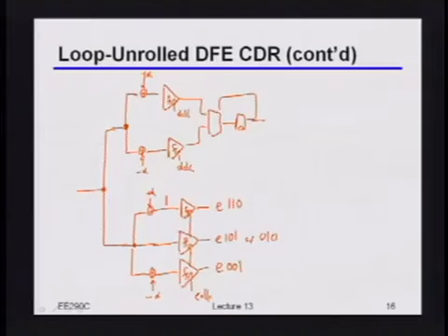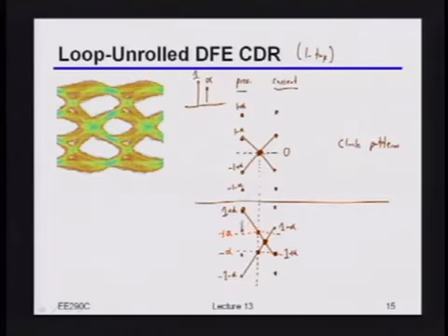But to do it live, I think has similar problems as what the normal loop unrolled DFE has, in the sense that there's really no analog level that you're looking for that gives you exactly that information. I guess actually, to be fair, the only saving grace here is that you really could look for this point in time here, but that would assume that you locked in the right place in the first place. Right, so I'm not exactly sure how you would check that, okay, are you really in the same time when you're doing the estimates this way versus that way?